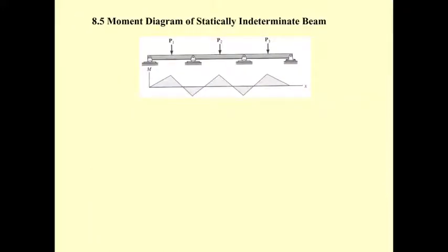Okay, the last portion of this clip, we are talking about the moment diagram, and I'd like you to recall when we were very young studying statics. We have the simple beam subjected to a point load. So we have the shear diagram like this, and we have the moment diagram like this. The point load is going to provide the moment diagram with a linear shape.